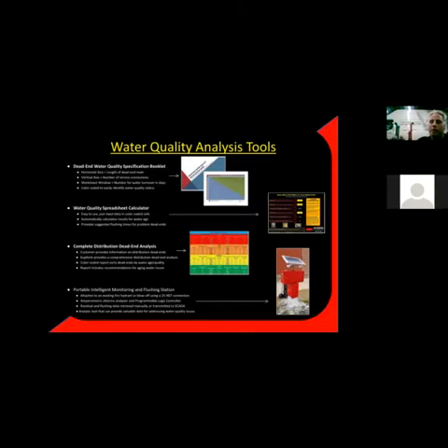So this is an analytical tool I can attach to a fire hydrant, collect data for a couple of weeks, and then I can move it around my system to different spots and see what's going on in different areas of my system. It's really a cool device to research water quality information in different parts of your system and find out what's going on. Then once you get the data from the station, you can make decisions on adding booster stations, automatic flushers, whatever you might need, or no action is needed at the time, depending on what comes back with the real data that you get from this particular device.